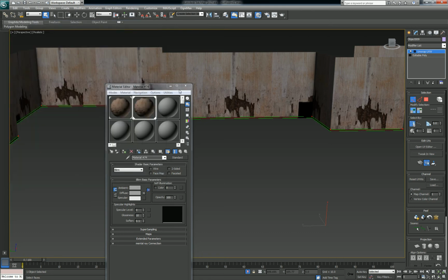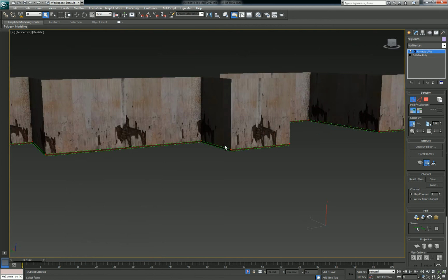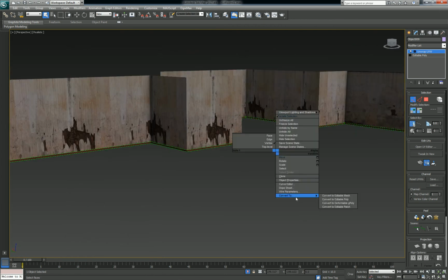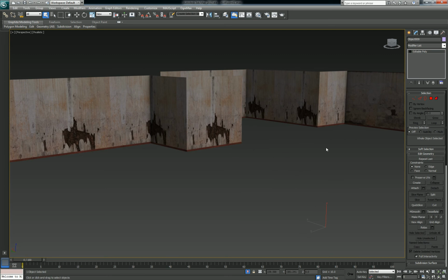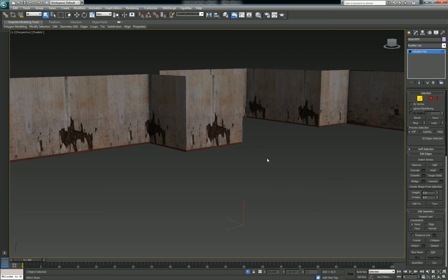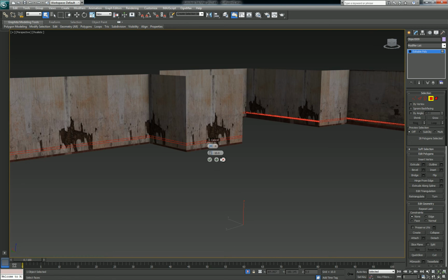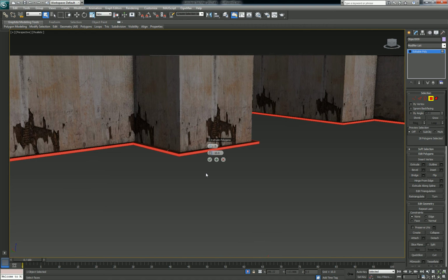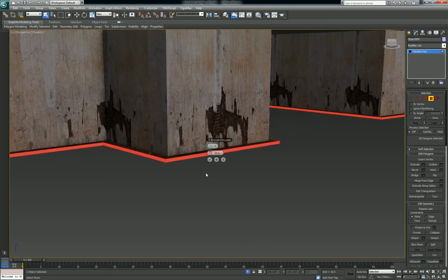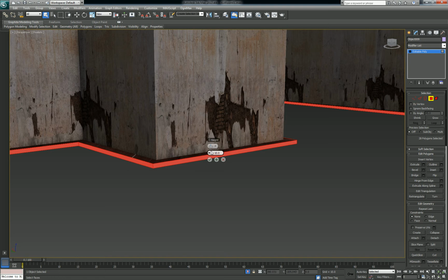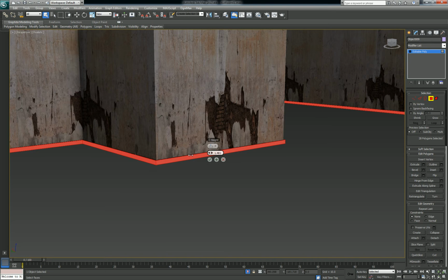But as we are now done with our edging all the way around, let's convert this over to an editable poly, and I'll select the edge again and convert that over to face normals, and we want a slight extrusion on it, which we want to do by local normals, but we don't want it to be too much because we don't want too much in the way of overstretching. Like 10 is way too much. I want that just to be enough to give a kind of a detached effect from the wall surface here.